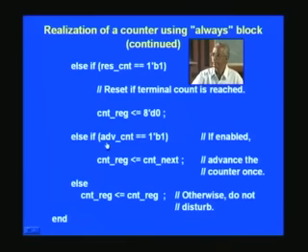So we need to advance if it is 1. We have already pre-incremented earlier using the assign statement, and now the clock will come only after a delay, because the clock strikes periodically at one particular point. At that point, whatever was the pre-incremented value will merely be pushed into this counter register.